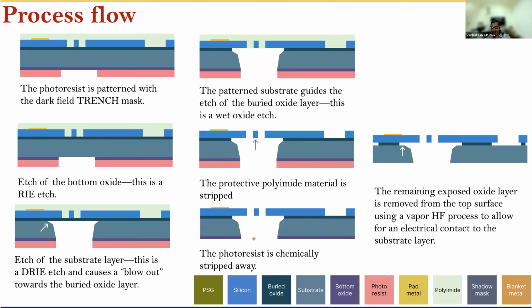Now you remove that oxide layer also, wherein you can basically expose it to wafer HF. Then you can remove the oxide as well. Now you will be left with just structures like this, right? So you can see that I had the oxide here as well. Both of them will get stripped away whenever I expose it to HF solution, because HF will enter from the top as well as from the bottom. So it will do the undercutting, and also it will etch away the complete oxide layer over here. So we can even get the electrical contacts.